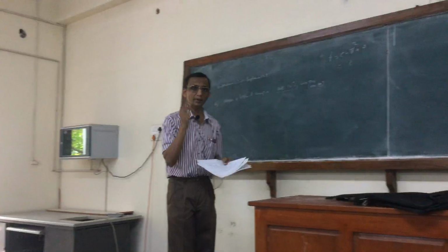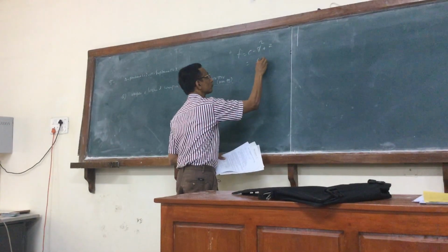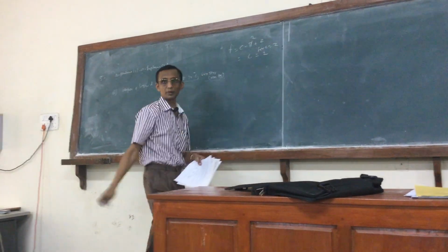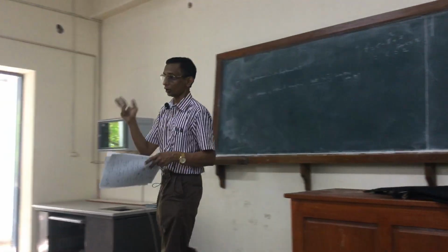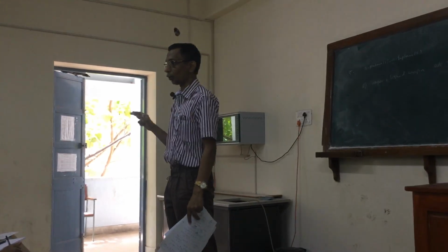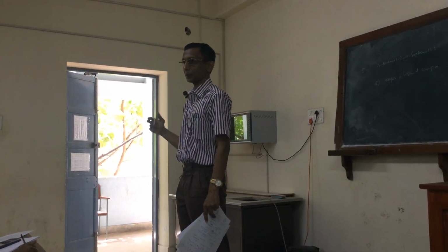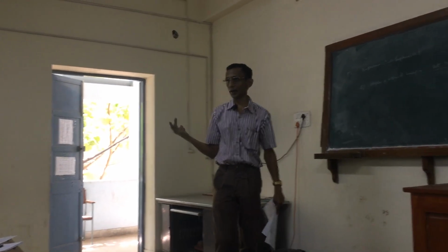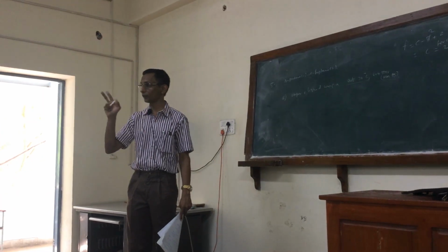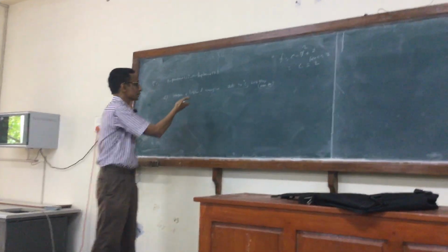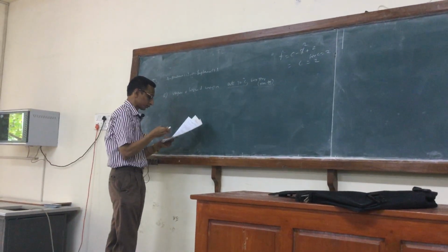However, for C equal to 2, the degrees of freedom will be 2. So I can talk of specifying the temperature and pressure and it will be completely specified. In no other case will just the specification of temperature and pressure be sufficient to determine the other degrees. So for a binary, with 2 degrees of freedom, this is a perfectly valid specification. The calculation for an ideal mixture is what you are asked to use.